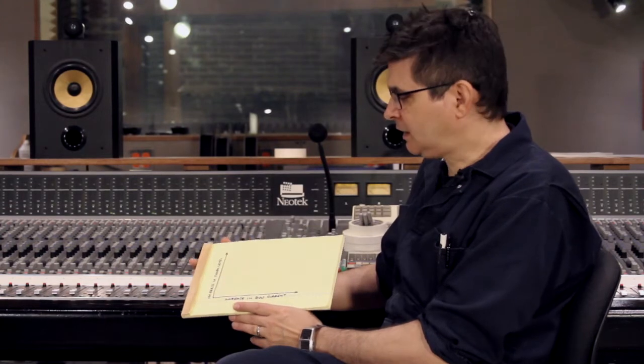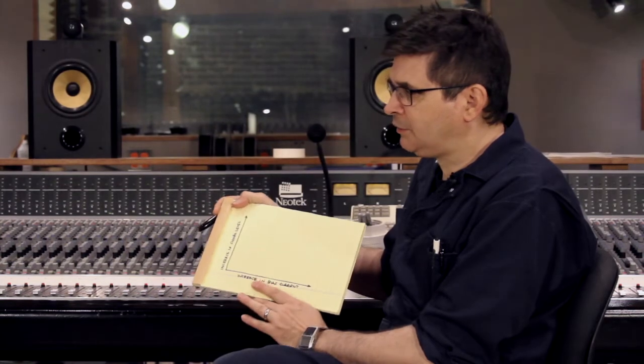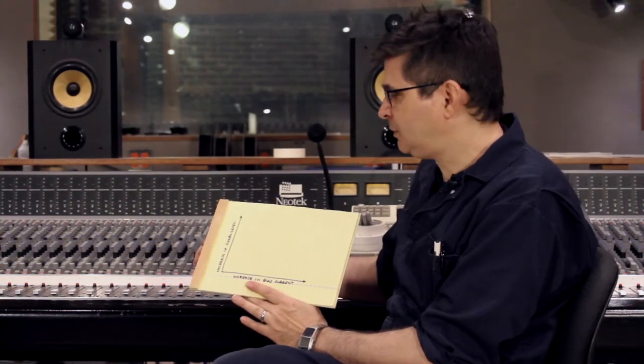The first step in calibrating the record alignment of the tape machine, after you've adjusted the azimuth so that the azimuth is correct and corresponds between the record and playback heads, is to adjust the bias on the machine. So I thought it was important to demonstrate and show you how the bias interacts with the other record electronics and the interface between the tape and the machine.